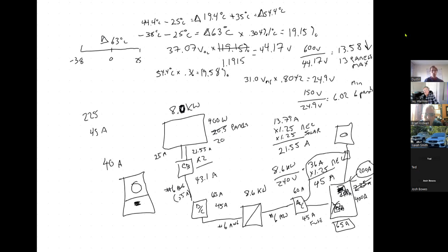And most of these have a couple of places for double pole breakers, so it's like a mini service panel right outside at your meter. In a case like this, you don't even have to go into the house. I could just come from my AC disconnect and connect right in here to one of these double pole breakers, and we should be fine. And that bypasses the main panel, but it's still on the load side of the meter, so it still works.